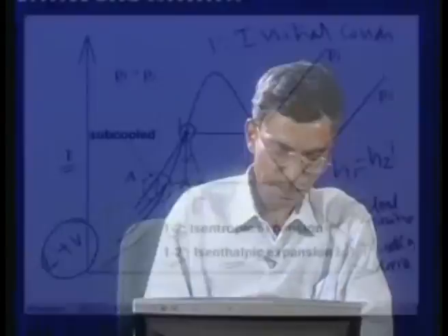So when some liquid flashes into vapor in an adiabatic device like a turbine or a throttling device, the temperature of the rest of the fluid has to reduce, because it has to supply the energy required for the vaporization. As a result the temperature of the entire system reduces. Here the system means the fluid which is undergoing the expansion. You must keep this in mind. The significant drop in temperature is taking place because during the expansion process vapor is being generated, and the energy required for vapor generation is supplied by the liquid itself. As a result its temperature drops. So this is the principle.